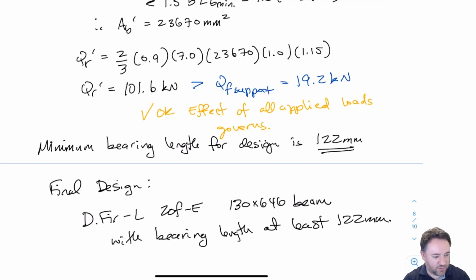So that's it. So over these two videos, we have looked at how to calculate the applied load and shear, and how to calculate what our minimum EI is for deflection. Then we selected a beam section from the tables in the design manual. Then we looked at our moment strength to make sure that that satisfied our applied moment.